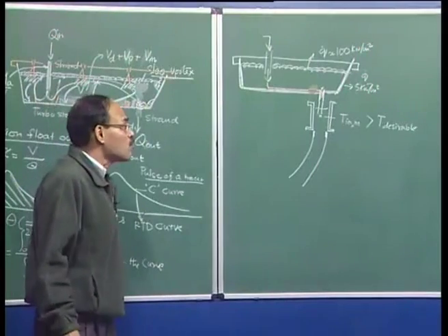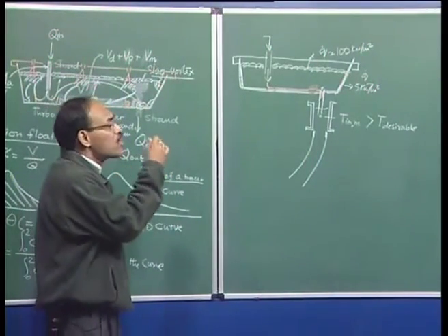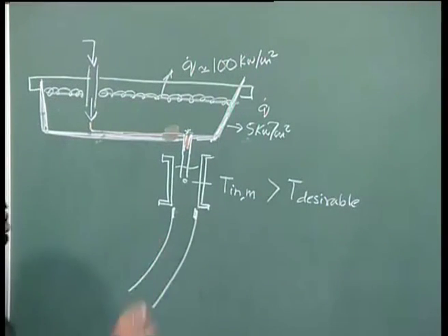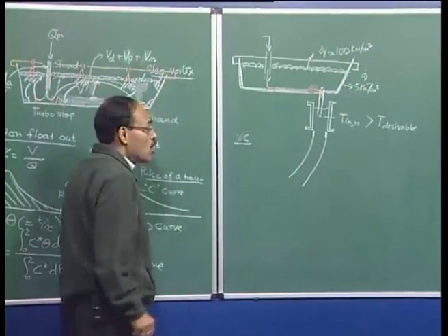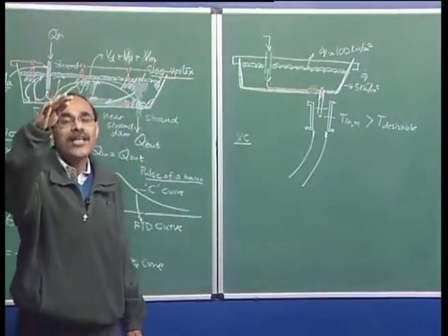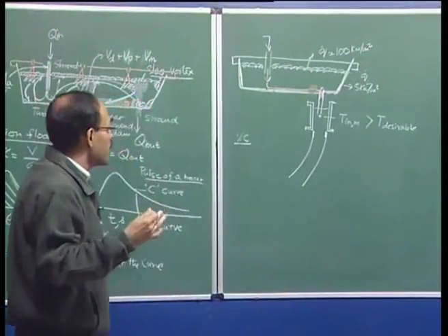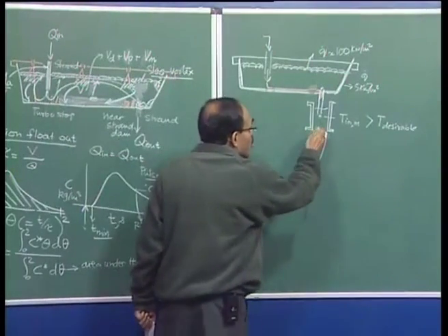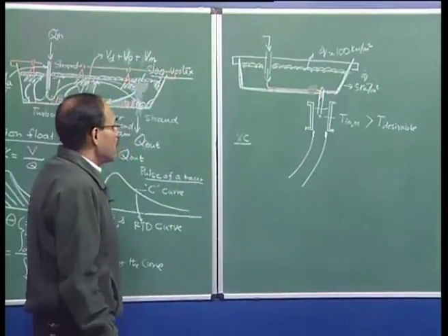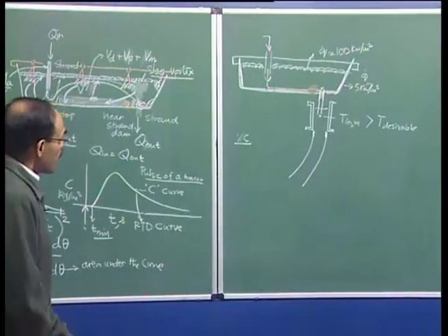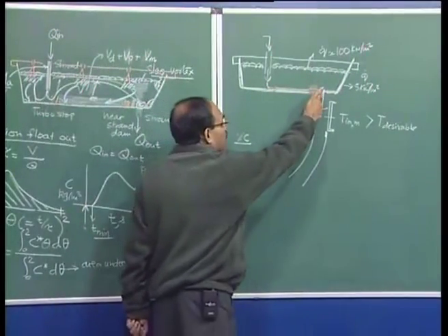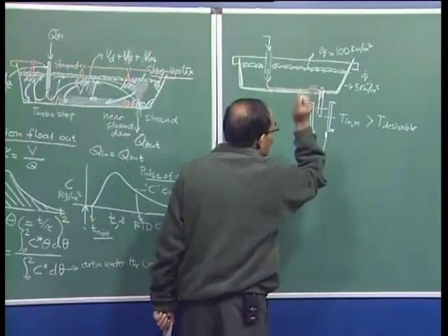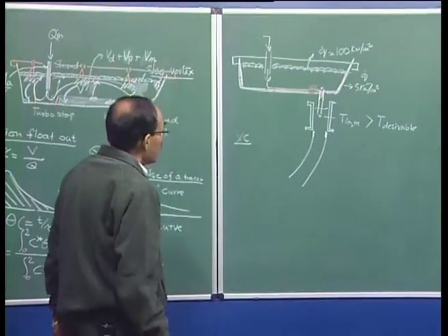the metal, and it is well known now that smaller is the superheat, the better is the quality of the cast product. By the by, what is the definition of superheat? So, if the steel has a melting temperature which is a function of carbon and other composition, the temperature over and above the liquidus temperature is termed as the extent of superheat. So, we are talking about desirable superheat here in the range of 15 degrees to 20 degrees, that is perhaps ideal. So, now if you have too large a temperature here, well, we do not want any premature solidification, then how is it possible for us to deliver molten metal into the tundish, into the mold correctly.